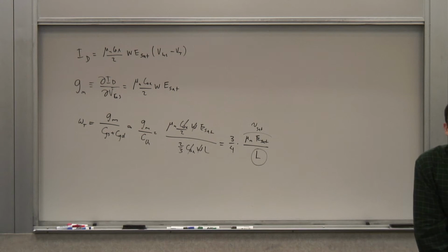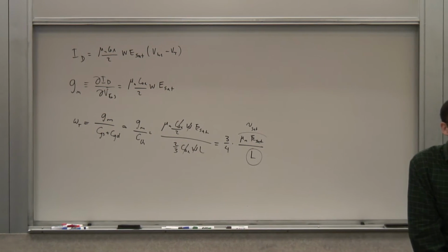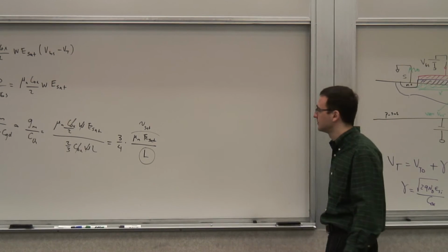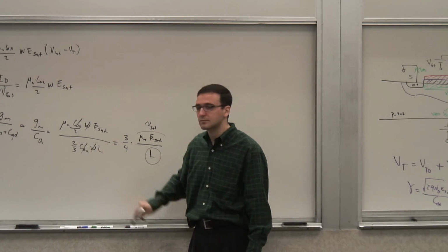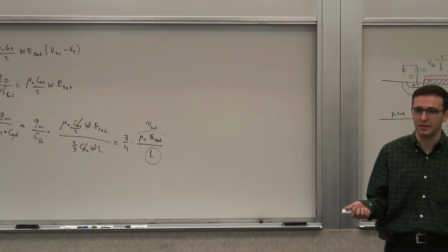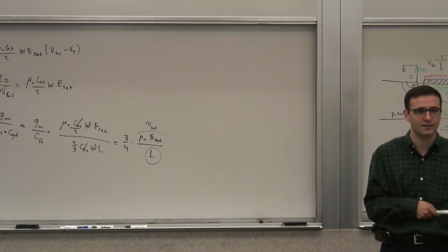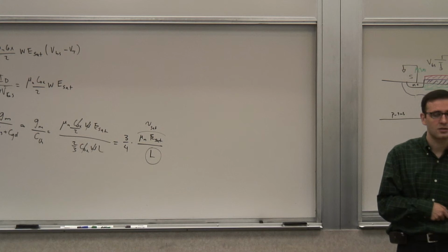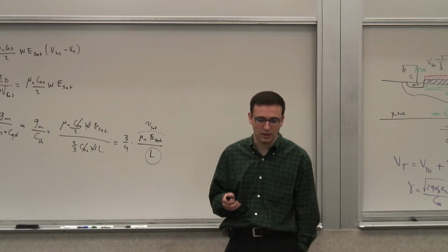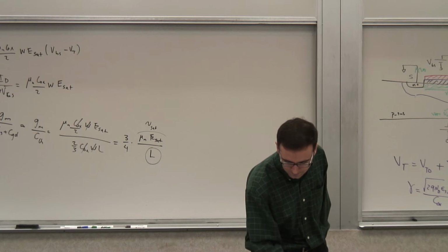Nowadays, we make them smaller not as much to get higher transconductance. We don't get higher transconductance. We scale them to get lower capacitance. And the improvement is only linear, as opposed to quadratic, because I have the same drive current, I just have to reduce the capacitance by making it smaller. Any questions about that?